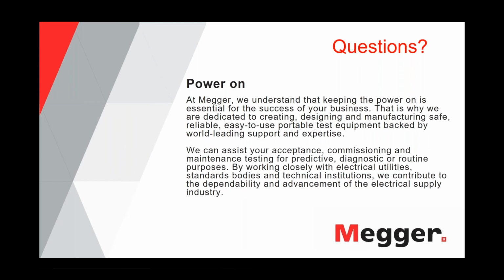All right. Well, now, like Javier was saying, the problem with basically both types of cables, solid dielectric and paper cables, is possible moisture ingress or water ingress into the cable. Now, on XLPE cables or solid dielectric cables, also EPR cables, this can be mitigated by putting either or both, one or two or both.